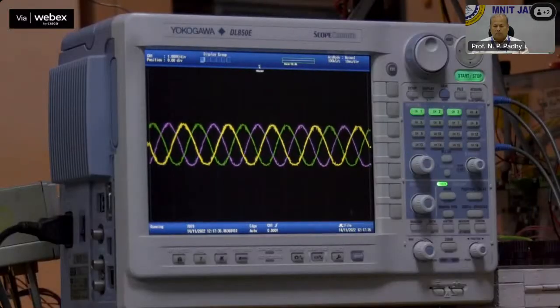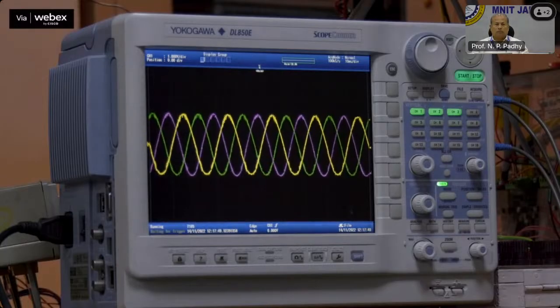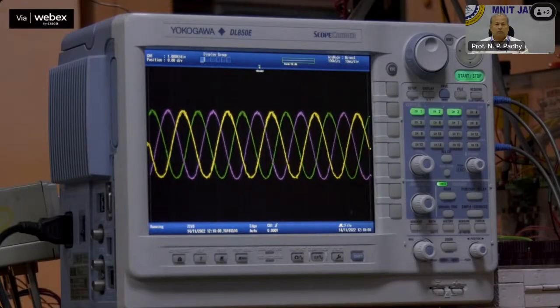We can see the 3-phase inverter output current waveforms are captured in the DSO. The current that we are seeing is fed to the distribution grid via the grid emulator. Now, the irradiance is varied in steps and the corresponding inverter output currents are captured in the DSO.